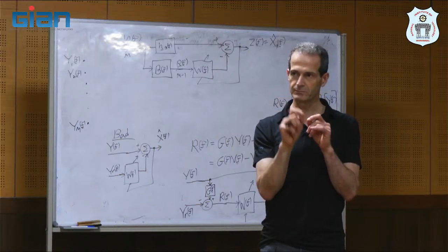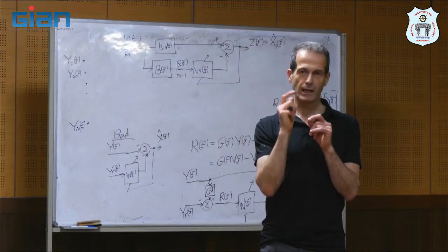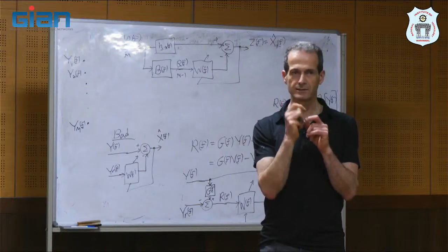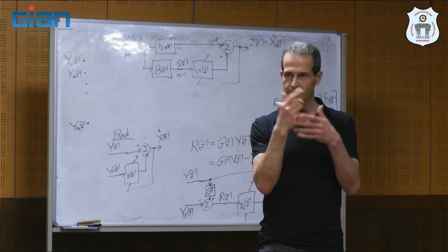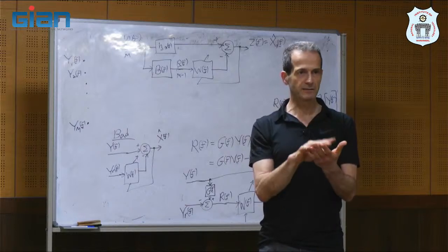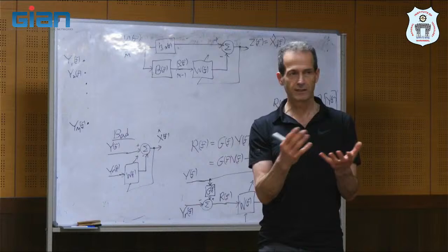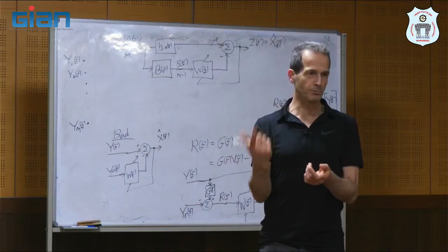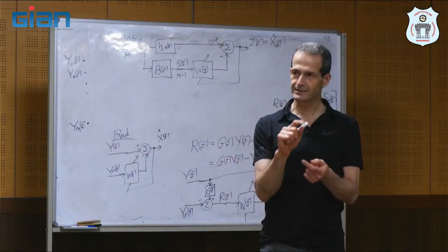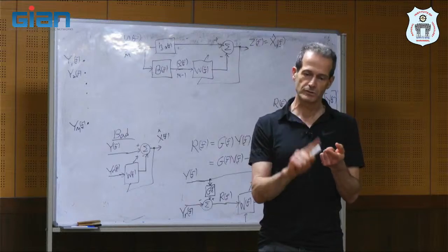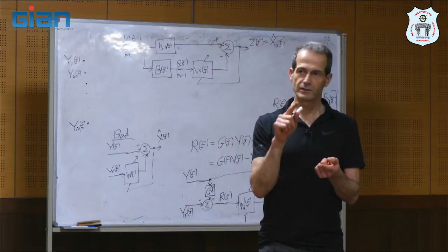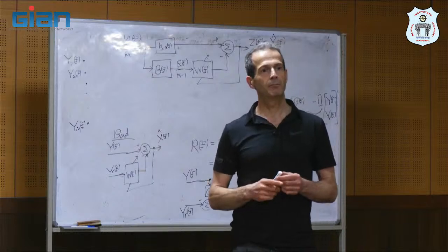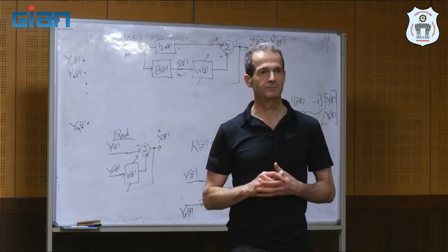Okay, so you transmit a signal, you get it back. What happens to the frequency of the signal that is received back from the target? It depends on the movement of the target. So we get a Doppler. And using this frequency difference, we can measure the movement. So this movement gives us a measure of the heart rate.